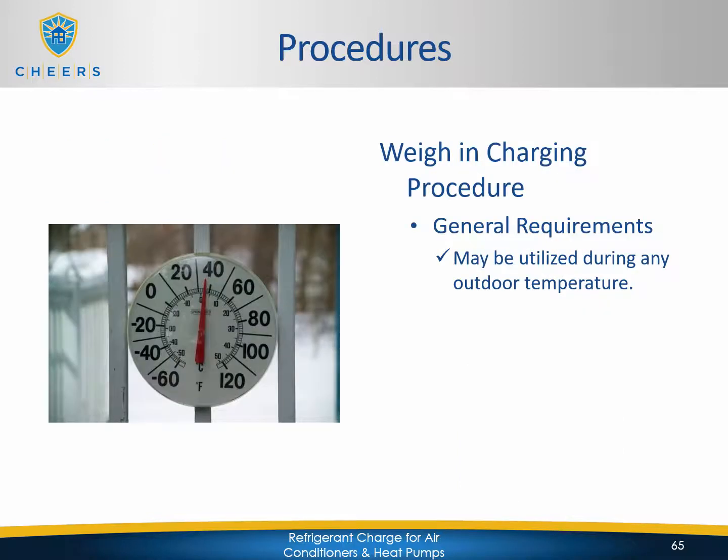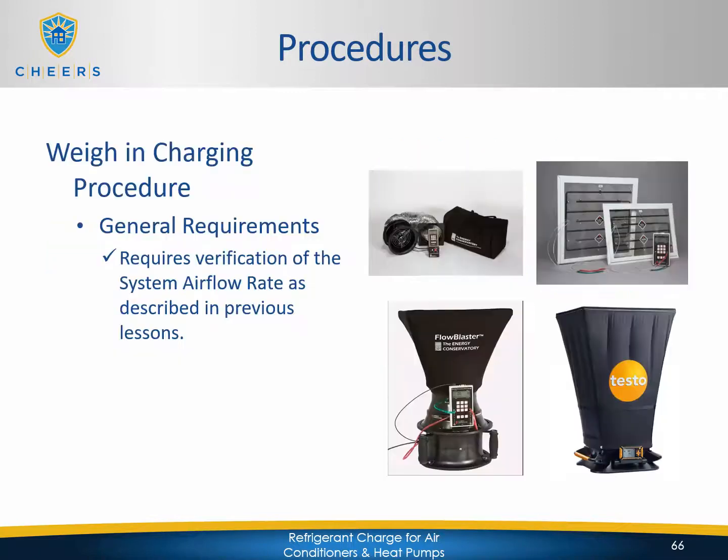The weigh-in charging procedures may be utilized during any outdoor temperature. And again, keep in mind that you as a HERS rater will not be conducting the actual procedure, but nonetheless you'll be observing the installer conducting the procedures and verifying that they're conducting it properly. It still requires verification of the air system airflow rate as described in previous lessons. So that requirement does not go away. You will still need to test for airflow and minimum airflow requirements.